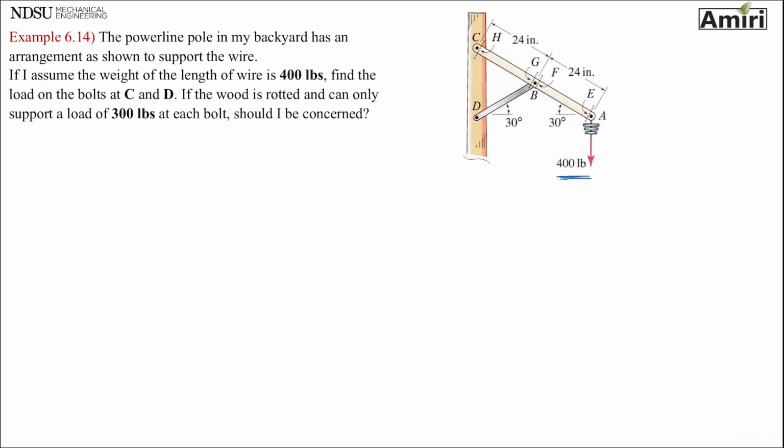First of all, this looks awful similar to a truss, but it's not a truss. Why is it not? Because of member CA. CA, sure, has forces at C, forces at A, but it has additional forces attached to it at point B, either in tension or compression.